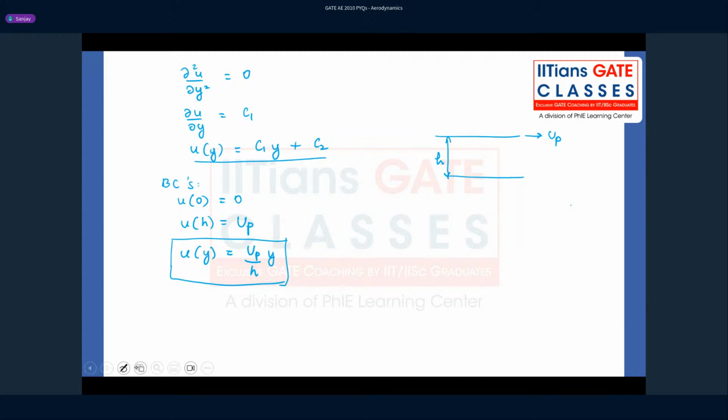So how is the velocity profile for this case? It is a linear velocity profile. Okay, it's a linear velocity profile. So this is what we had from our intuition, and we have obtained that mathematically also from the Navier-Stokes equation.